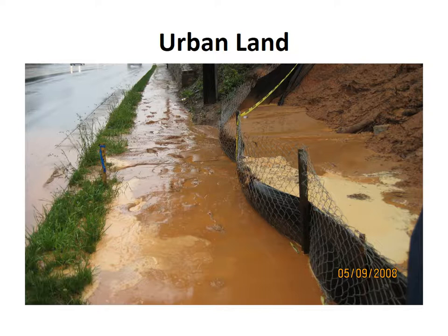During the construction phase of development, abnormal amounts of sediment, as well as runoff, may enter creeks. The use of temporary sediment fences may reduce the delivery of sediments into the creek, but often fail to control sediment adequately during large runoff events. After construction is complete and pavement is installed, sediment load is often decreased while runoff is greatly increased. This combination leads to severe erosion of banks and the bottom of the channel, since the hungry water, free of sediment, has greater energy with which to cause erosion.